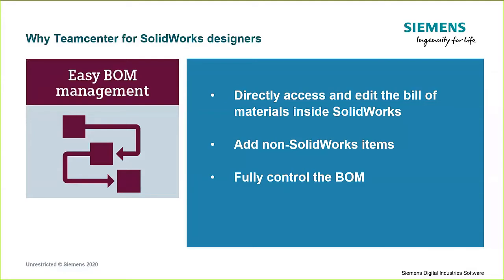All right, let's move on to another topic, bill of material management. So with SolidWorks, you can really only view the mechanical CAD BOM in your PDM client. And from a search standpoint, you may be able to search and drag and drop some CAD parts, but the search isn't as fluid as what you'll see with Team Center. And then what about if you want to add some non-CAD items? So whether it be grease or paint or adhesives or other types of lubricants, how do you add those to the BOM? A lot of times that's challenging.